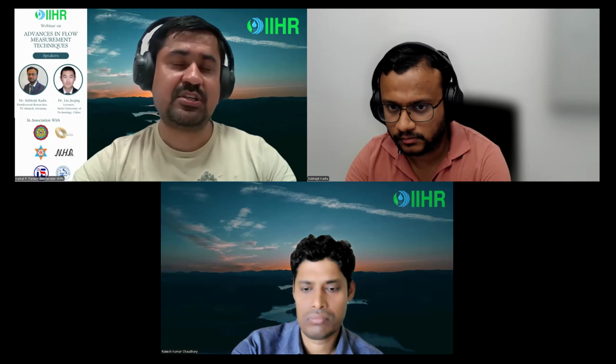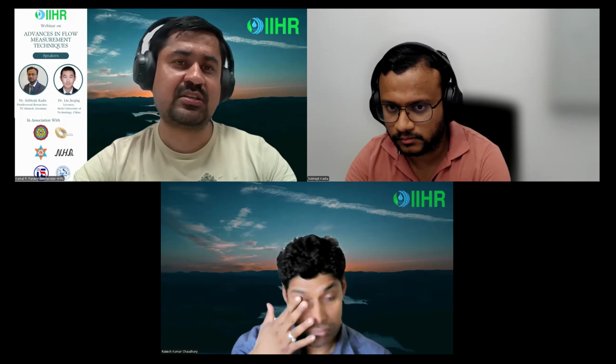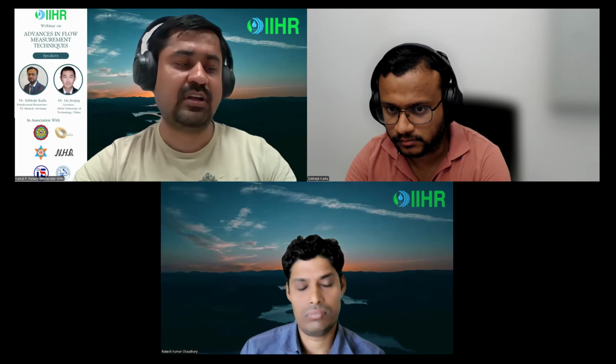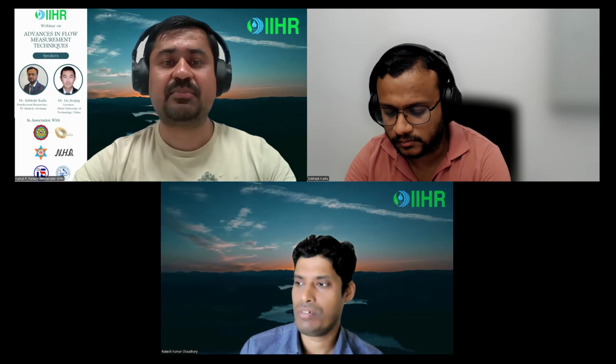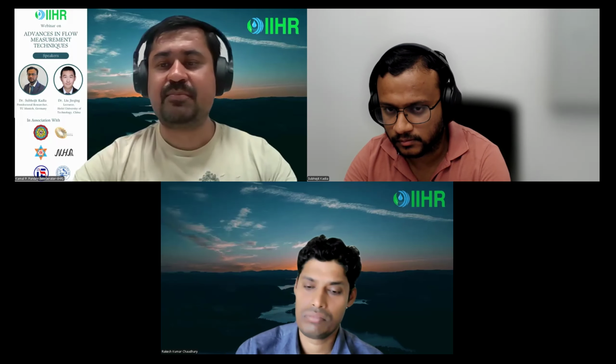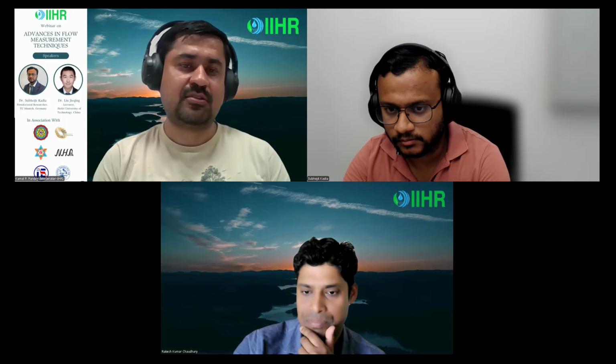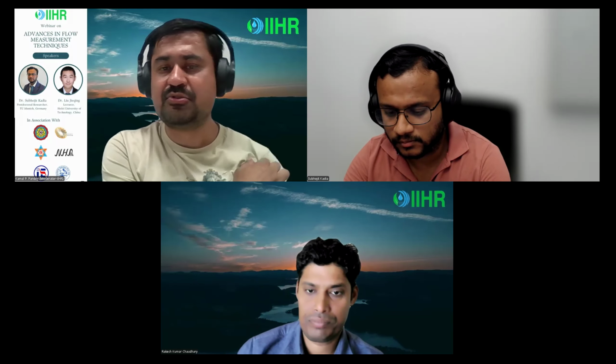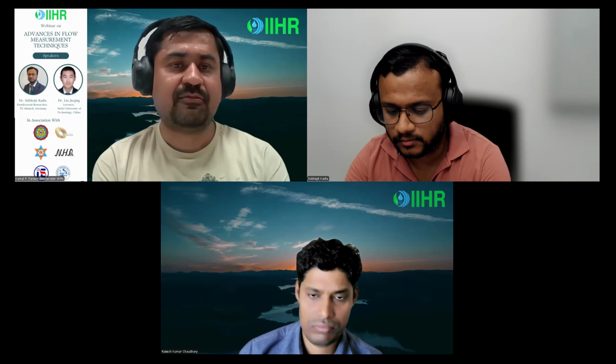So there are some PIV setups that use a mild type of laser that can mostly characterize the flow field, like the 3D flow field inside the real river. And as for the PTV, it is also used in the field to get the 2D flow vectors. There has been some progress in the field, and in the near future, I think we can have a viable solution which can use both techniques to get a more detailed flow field as well as the particle characteristics,